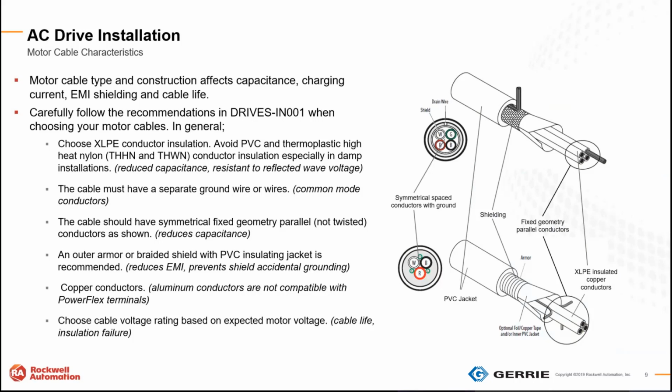Next thing I was just going to briefly talk about was the motor cable characteristics. I'm going to refer quite often to the recommendations in our drives IN001 installation manual, and in there we specify what type of cables to use. In this case we're using an EMI shielded cable, and the specifications are down below, you can see there.